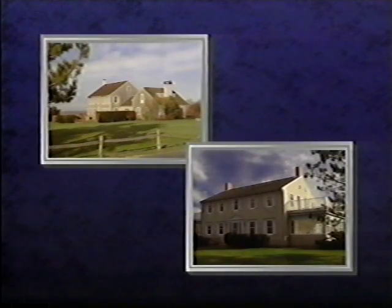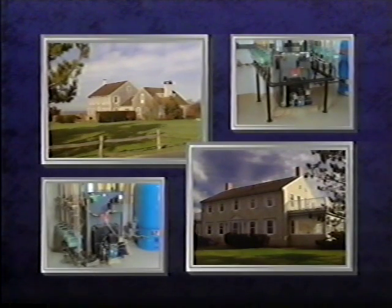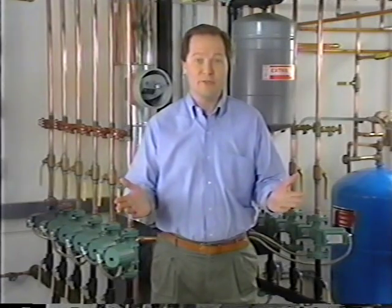In recent years, residential construction trends indicate more larger, multi-level homes with large glass areas and fireplaces. Because of these large window and door areas, zoning the heating system can compensate for these trends in building construction with different heating requirements. By reducing temperatures in room areas such as bedrooms, zoning provides for a more efficient heating system operation, reducing fuel consumption.